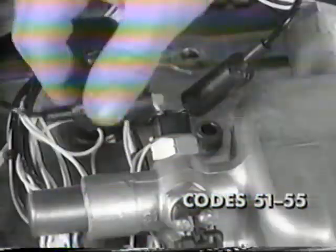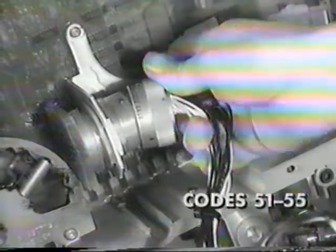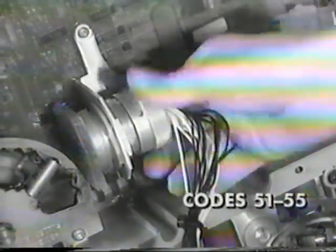Now, there are 3 important things to remember when you're done here. Don't forget to remove the jumper wire from the ball switch. Reconnect all of the connectors, including the switch and the auto shifter harness. And don't pinch the wires under the shift bar cover. You don't want to create a new problem while you're fixing an old one.